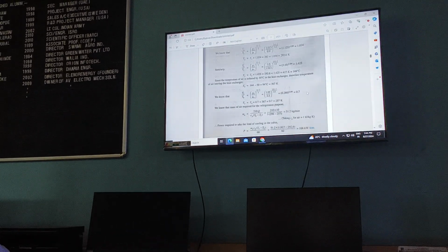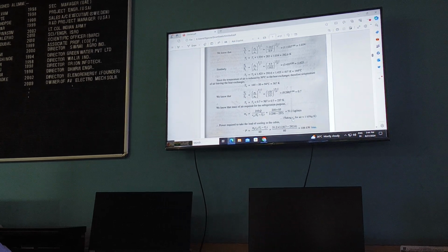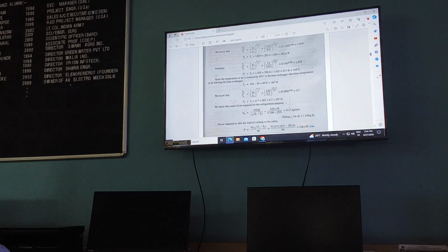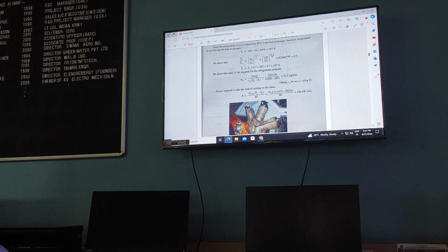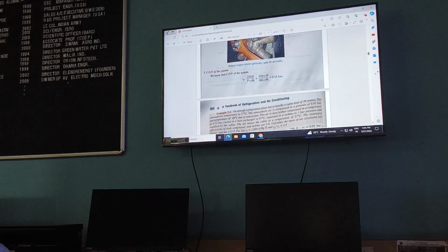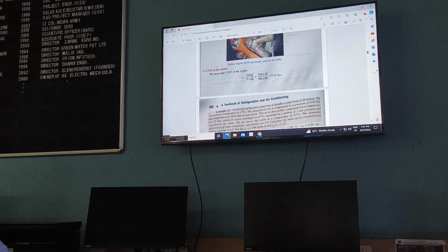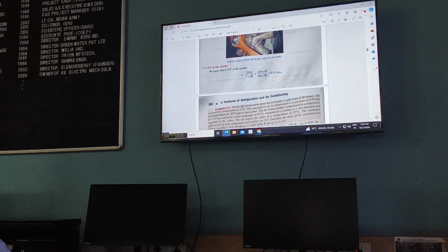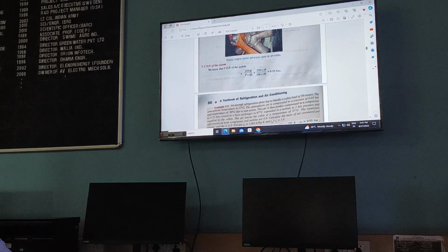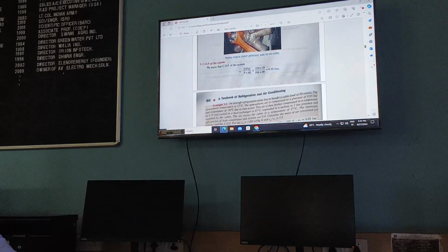Okay. Straightforward: calculating temperature, calculating mass straight away. If Cp is not given, take it as 1, then power in kilowatt and COP. And always remember, COP of an air refrigeration system is less than 1. It is generally around 0.2, 0.3, 0.4, 0.5 or at most 0.6.